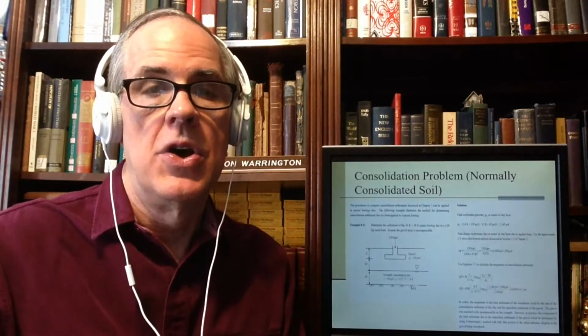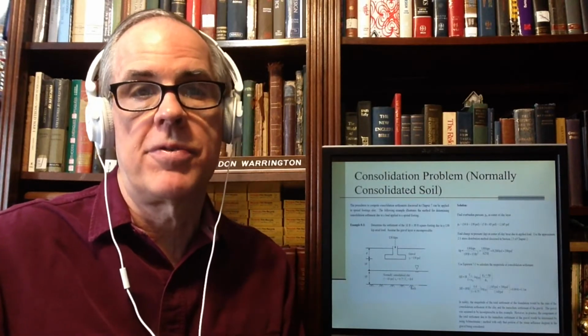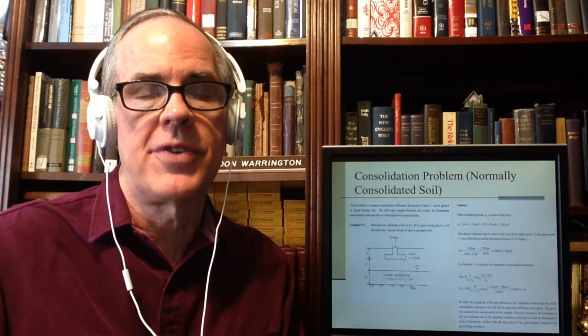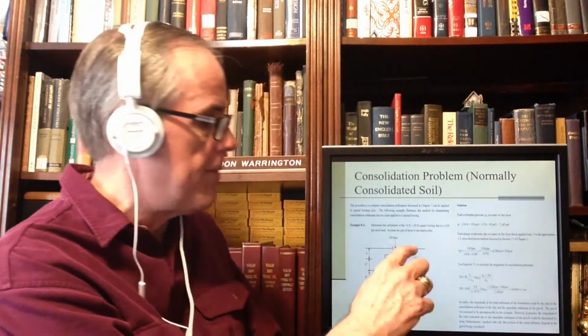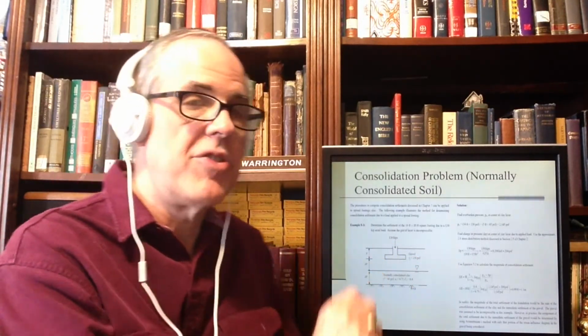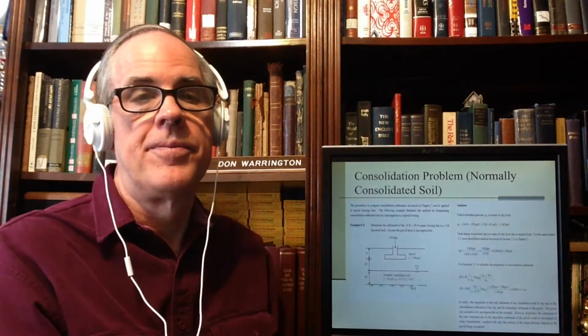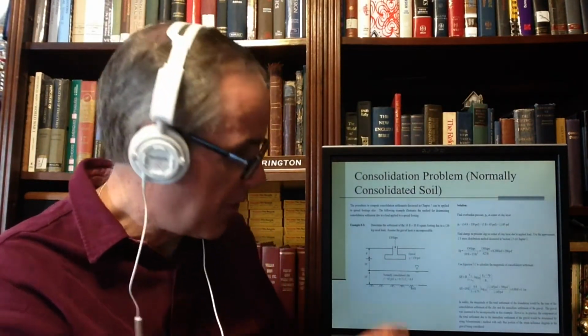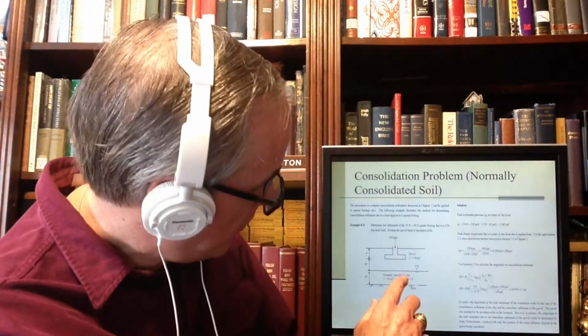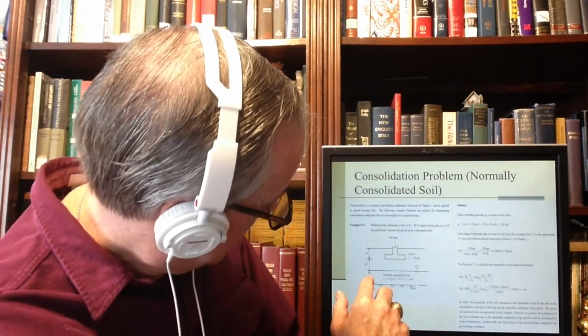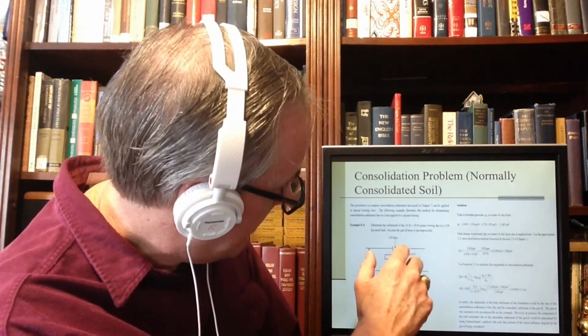That's 15 feet. One thing you have to be very careful about with these problems: it's the exceptional shallow foundation that is done on grade, in other words, at the surface. You obviously have to compute your effective stresses from the surface, but the stresses the foundation induces, the delta P, start at the base of the foundation, and the base of the foundation isn't always the surface. It's usually below it. So don't get this messed up. Just because you went down 19 feet to get to this doesn't mean you use 19 feet to get that. You start from the bottom of the foundation.